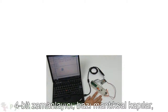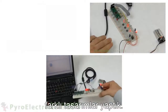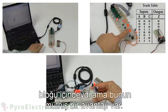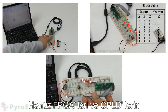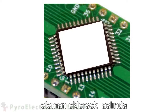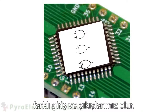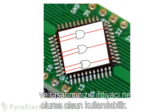Throughout this course, we have built a 4-bit timer, some combinatorial logic, simple input and output buffers, and many other designs. All of these designs were a single process or logic block inside of our CPLD. But there's a great advantage we have yet to explore in FPGAs and CPLDs, and that is using hardware in parallel. If we look at our CPLD and add 3 basic logic elements, it's actually possible to have each one operate in parallel, with different inputs and outputs. In this way, each logic element is independent of the others and can be used for whatever your design requires.